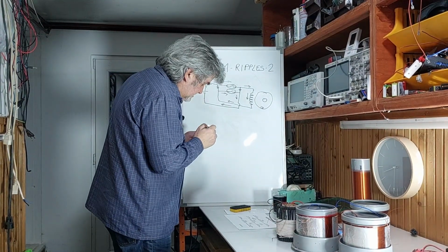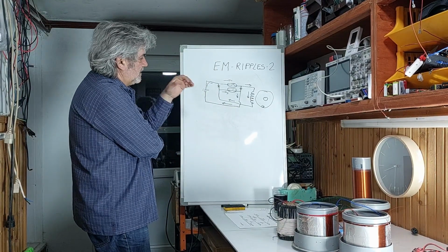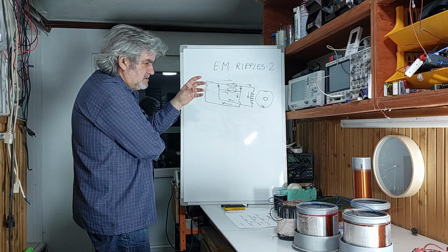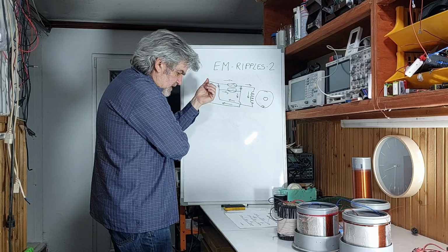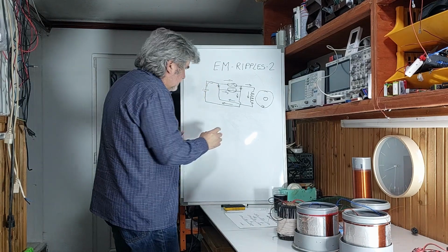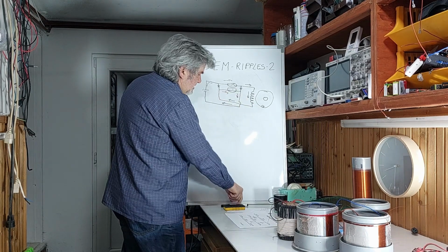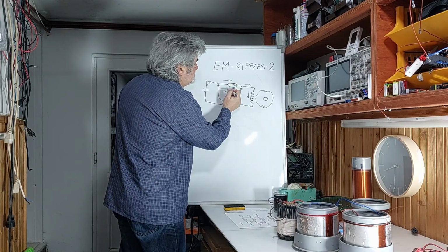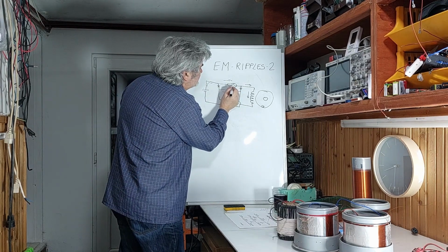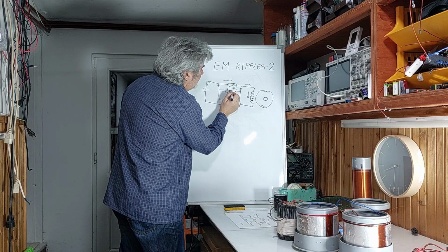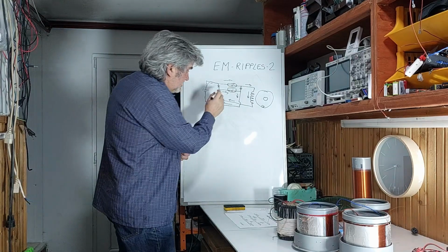But it's not exactly what I said. Ordinary, very common reed switches are rated at about 100, a little below 200 volts. Because of the powerful back EMF, even when the reed switches are open, some current will pass here, so you need to care about that, to avoid this with capacitors, but you don't have to.